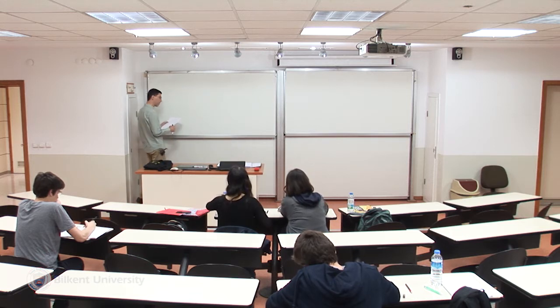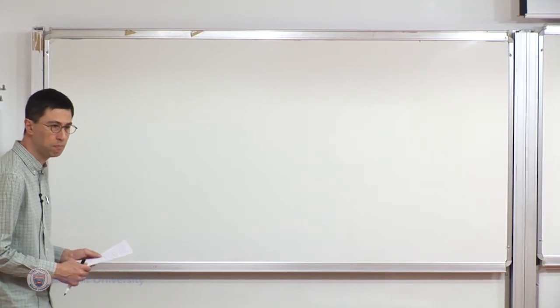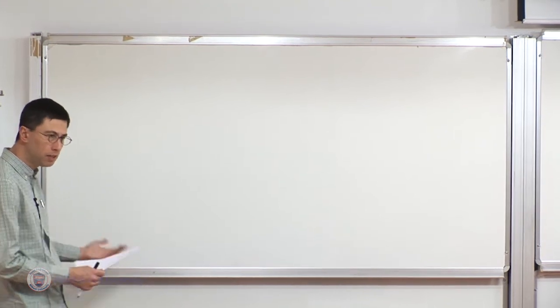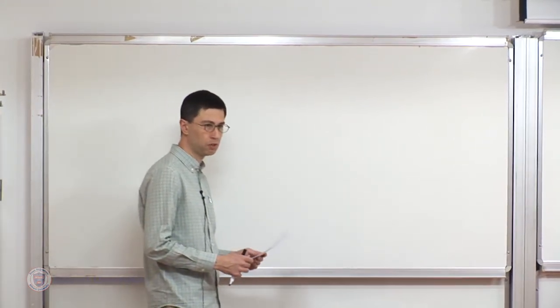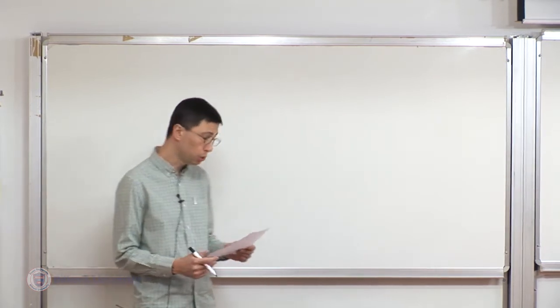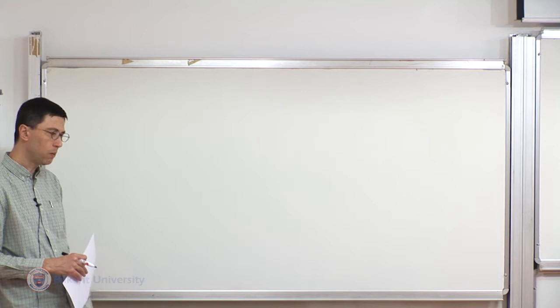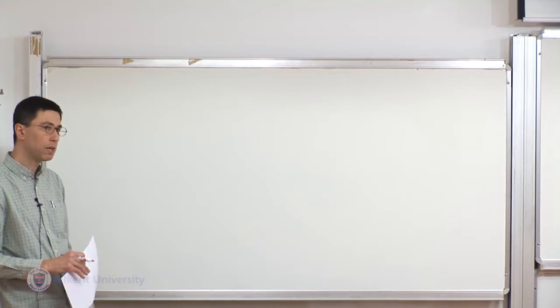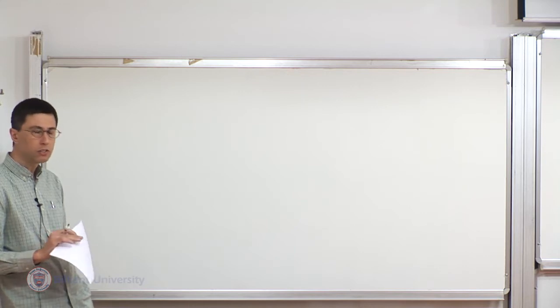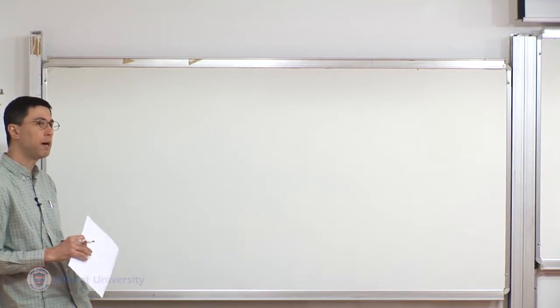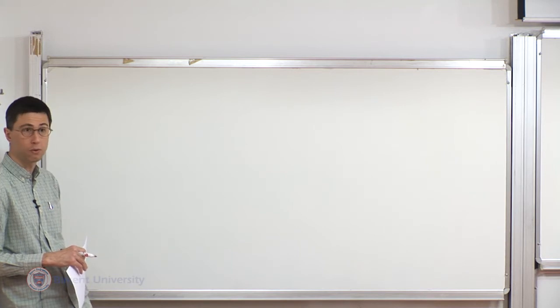We are talking about an approximate solution of problems of the beam geometry. And we have already solved this problem analytically, which is supposed to be a very good approximation to the, let's say, exact solution under appropriate circumstances. But a beam solution is something that we desire to have if it is applicable, because a beam is a one-dimensional theory. Versus an analytical approximation or a numerical solution of the exact three-dimensional geometry, a one-dimensional approximation is numerically a lot more efficient.